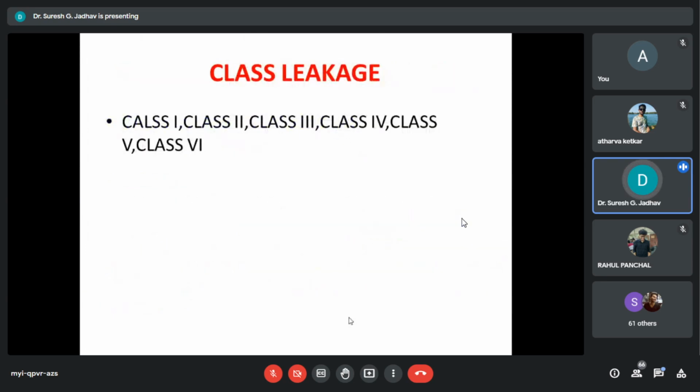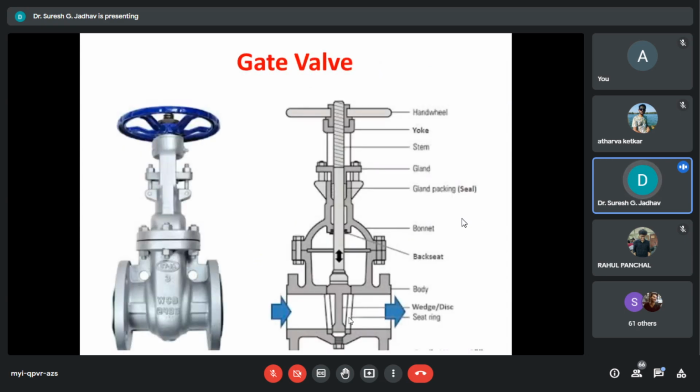The flange connection shall be ANSI B16.5 or any of the flange standards. The butt welding end connection shall be to ANSI B16.25 or any other end preparation required.